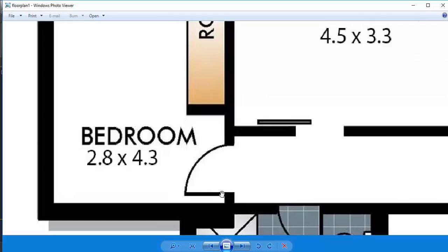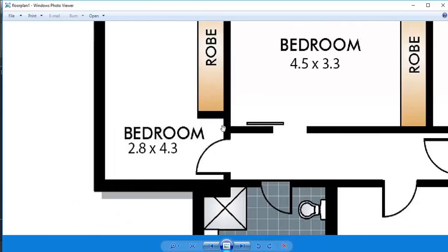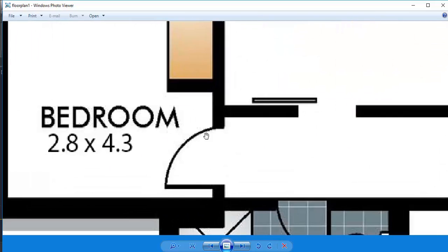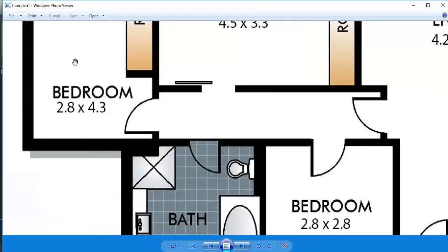And people look at that and just look at the plan and think, that gives me less space and makes it harder to get in. But it actually gives you more privacy. And also, the door, remember, can open all the way back to the wall, so it's not going to restrict access all that much. And privacy is a big issue, so that is the traditional way, to have the door opening and blocking the space, not like this, where when the door's open, you lose all privacy. And so it's a common mistake people make.